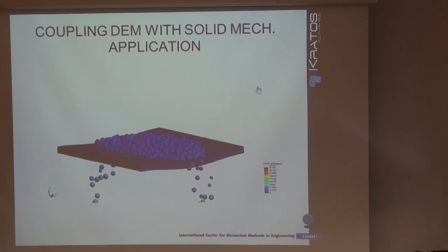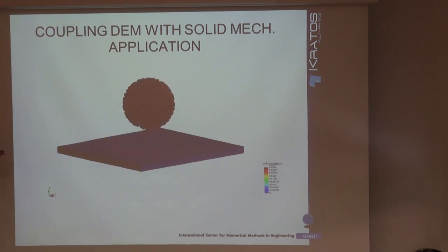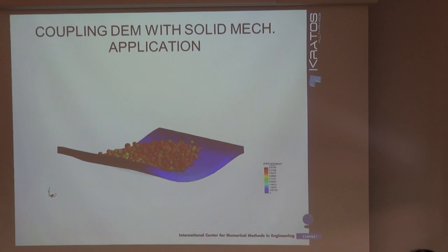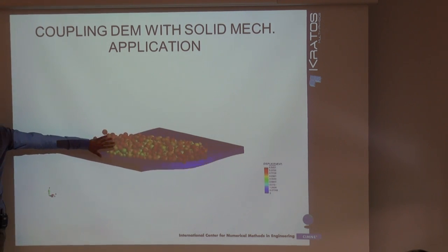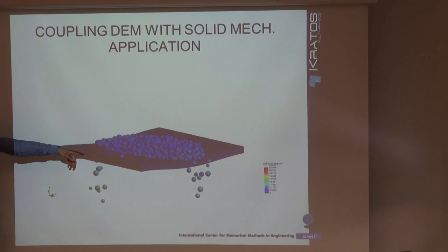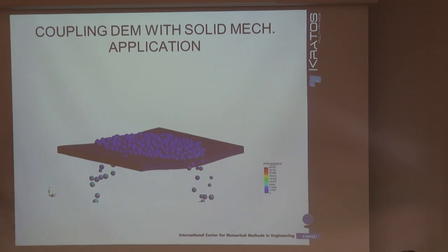When you get into Kratos and you want to be a developer or advanced user, you can code and combine different strategies. In this case, there is a solver that solves for the particles and communicates the forces with the structural application, and then there is a solver that solves for this structure. And I can use all the elements that are available in the solid mechanics application. So this can be small displacement elements, large displacement. I haven't coded it. I just dealt with the particles, but then I just call one solver and one application and the other one.